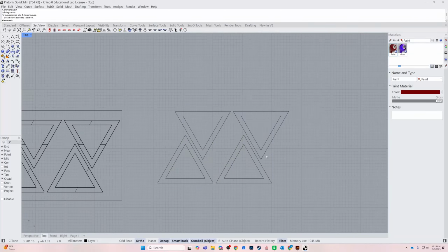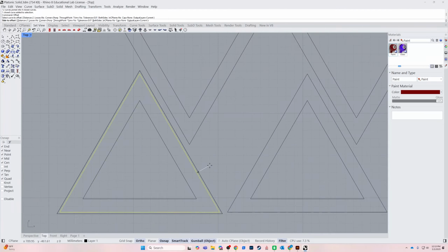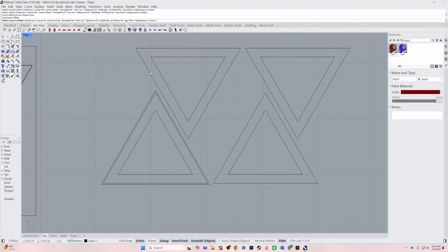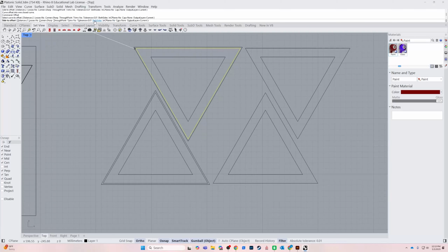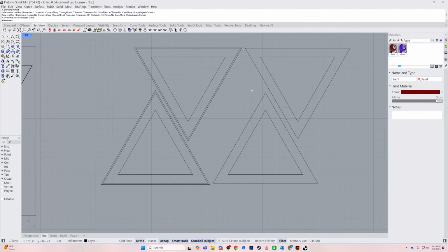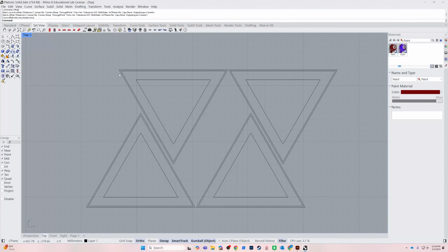Okay. And then I'm going to offset this one here, 2 millimeters, this one here. And if for some reason it's not offsetting the way mine is, with your corner sharp right there, that's what you would need to make sure is on. Okay. All right. So that gives me my offset now. So that's what we're actually going to cut. This area right here is what we're going to then have our finished dimension to. So we'll cut that on the bandsaw.